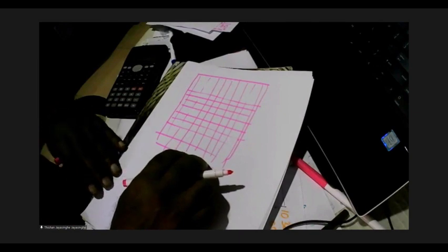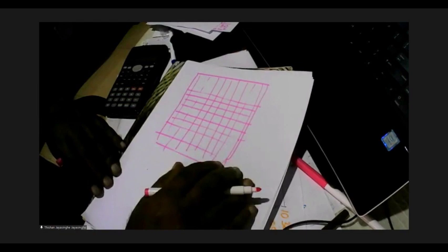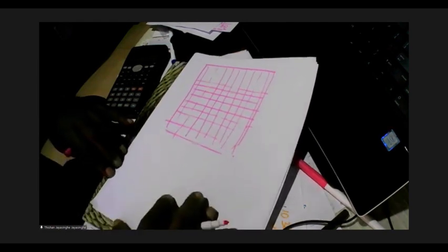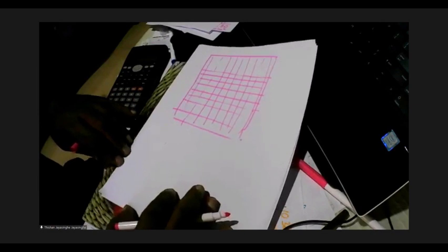So in the middle strips, you will apply a little higher pre-stress. You will concentrate the tendons in the middle strip and have fewer tendons in the edge strip. So that is something that some engineers do, because it will give better ductility. Now let's see how the tendons will come.